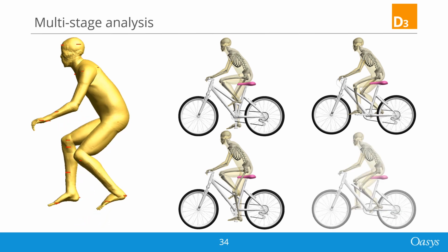Here, Primer has created multiple sets of cables in series and written out the Dyna input file at the end of each intermediate stage. This approach allows the user to specify several different end positions in one analysis, so slightly different positions can be achieved without having to go back and redo much of the initial part of the analysis.